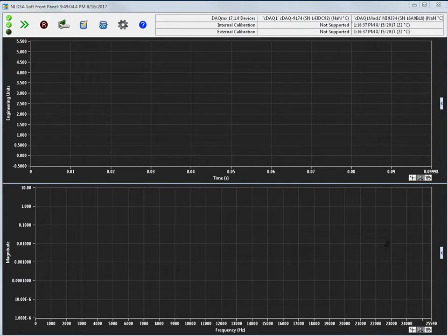The NI DSA software front panel provides a graphical interface for configuring DAQmx analog input hardware and performing interactive cursor-based inspection of time and spectral data. It has status LEDs that return the verification status of the DAQmx analog input task, acquisition, and software trigger. Application control buttons are in the ribbon at the top of the main application UI. System and device information are displayed in the top right table. The top graph displays the time domain waveform, the bottom one displays the discrete Fourier transform.